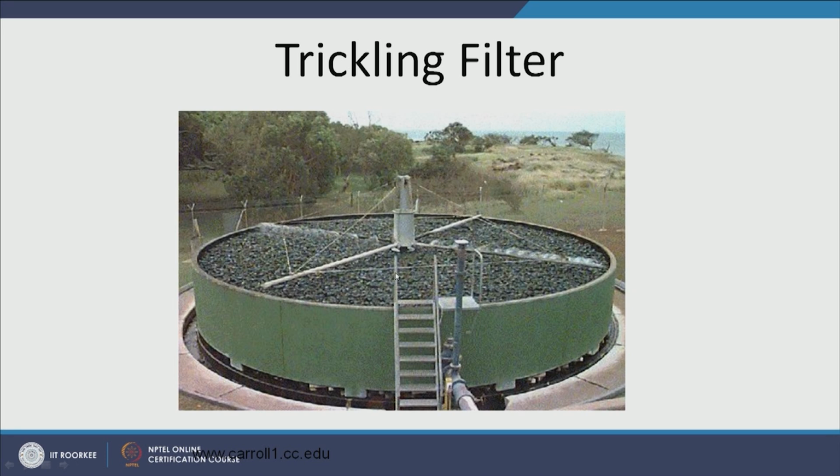So, this is your wastewater that has already undergone screening, grit removal and primary settlement, and then this is thrown on this filter, and there are biofilms growing in this filter, and what trickles out here is your treated water. So, this then can be taken for disinfection.